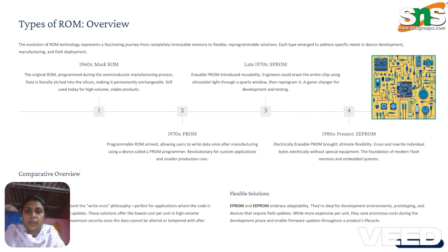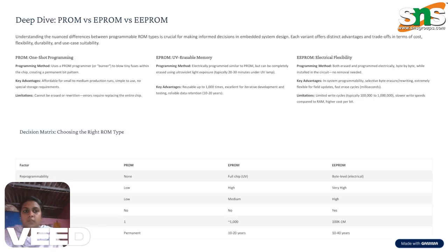And then next, types of ROMs, the overview. Read-only memories come in several types, designed with different levels of flexibility for programmability and reusability. These variations allow engineers to choose the right kind of ROM depending on the application's needs, whether it requires permanent storage or the ability to update the data occasionally. So the ROM types are PROM, EPROM and EEPROM.